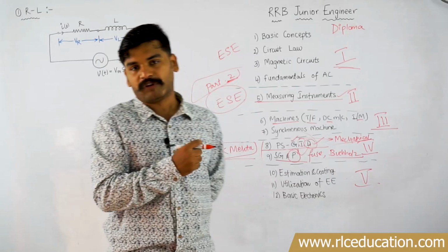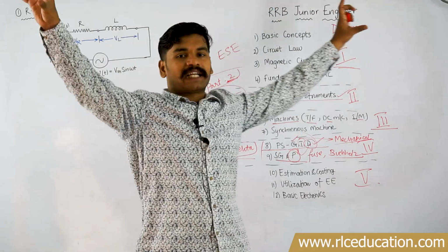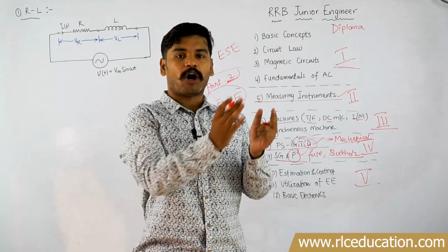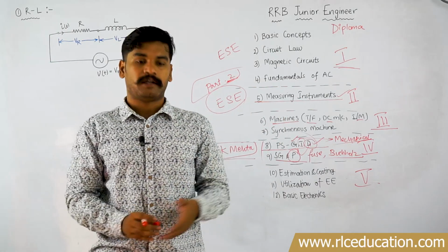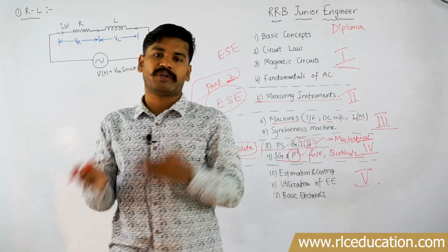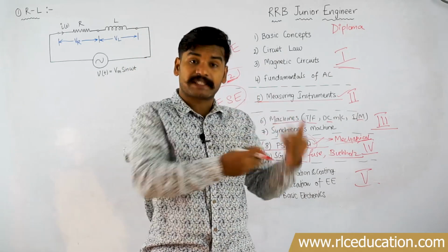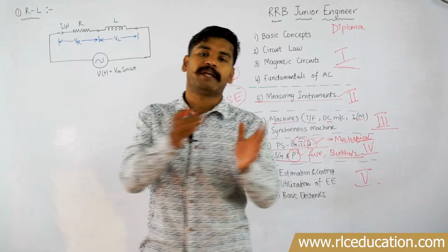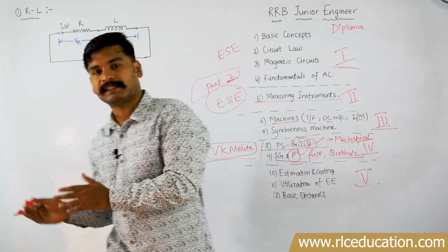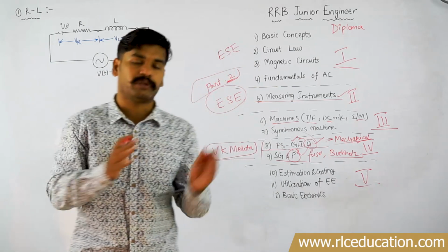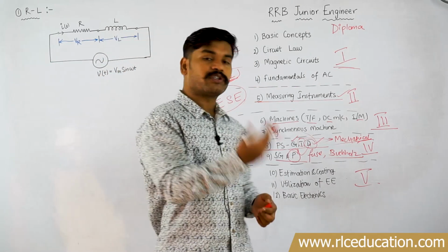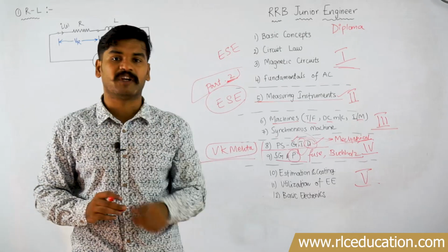In electrical designing, what we do is model this entire big transmission line in the form of circuit elements, that is R, L, C and G, isn't it? Based on their relative distribution, you classify them by the physical length of the transmission line: short, medium, long, and there are the ABCD parameters. This is called electrical designing, where you study the performance, like efficiency and voltage regulation.